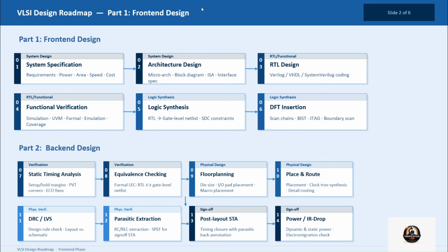The power integrity analysis to avoid voltage drop, EM failure, and thermal issues. How does it analyze? Dynamic power, leakage, then your IR drop, migrations, all these things. Fine.